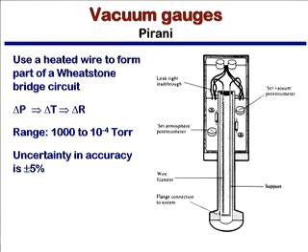For relatively low pressures, things between room pressure and down to about 10 to the minus 4 torr, we use what's called a Pirani gauge. And really the idea here is that you use a heated wire filament. You put that wire filament in the center of a Wheatstone bridge so that you can sensitively detect changes in the resistivity. And what happens is as you change pressure, right, you get different particles impacting that wire filament and carrying different levels of heat away from it, okay?